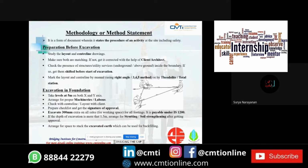So next concept is about methodology or method statement. It is a form of document wherein it states the procedure of an activity at a site, including safety. So before excavation, these are the following things to be noted before preparing for excavations. We should study the layout and center line drawings, and make sure that both are matching or not. If not, it should be corrected with the help of clients or architects, and check with the utility services inside the boundary. If anything is found, it should be shifted before the start of excavations.